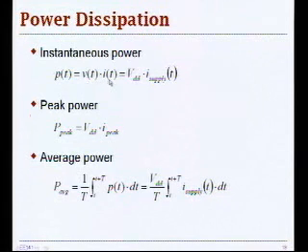This is applicable for any node in your circuit, but we are mostly concerned with the global power consumption out of our supply voltage. For that reason, we normally look at VDD, which is constant over time, times the supply current that changes depending on the switching events and so on.